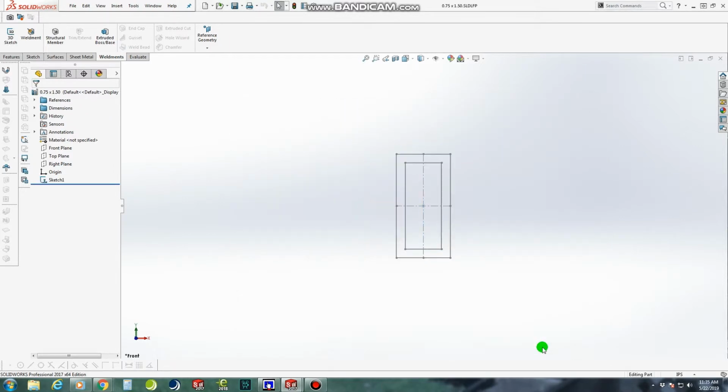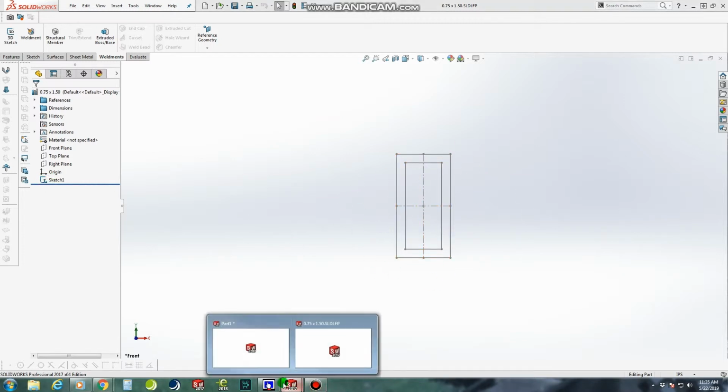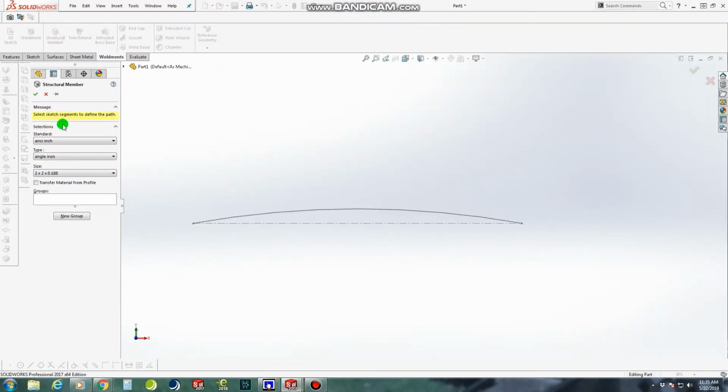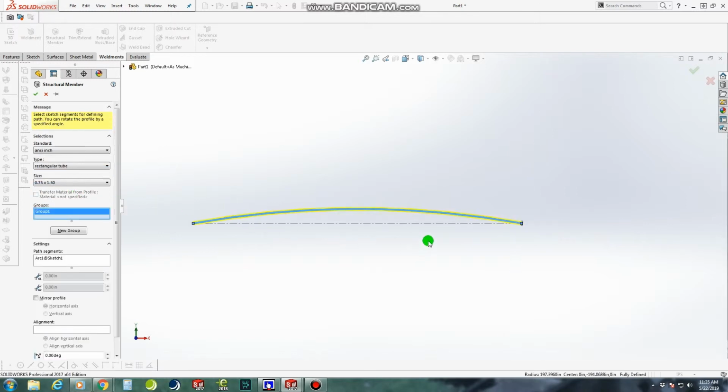And we save. Okay, now we notice that this sketch is saved with this little L, so that means that it is saved as a library feature part. And now we should be able to go back into our part here, go to our structural members, and we can take, oh, it did not show up. Oh, because we're in angle iron, that is my bad. And there it is right there. And groups. And there we have it.